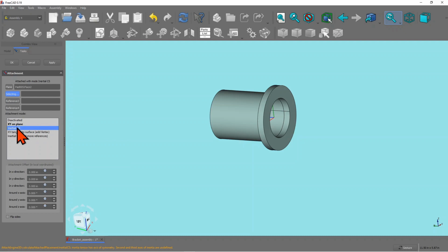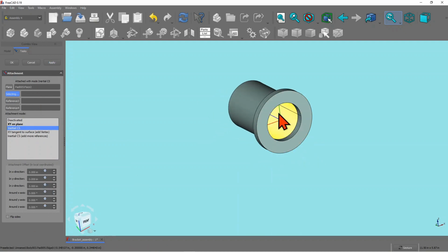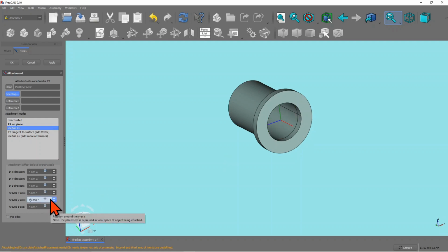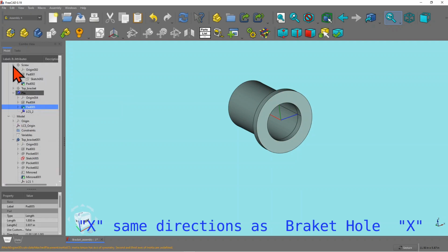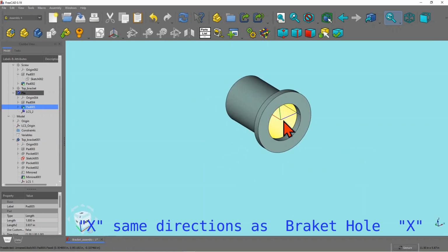So anyway, the only thing I need to do now is to rotate it about Y. Let's see what can be done here. Okay, so I'll rotate it the other way. I'm going to say -Y and say okay. Now I want it the way it is. Going to say okay, get out of it. Now I have a local coordinate system defined in the pin. I'm going to recompute it.